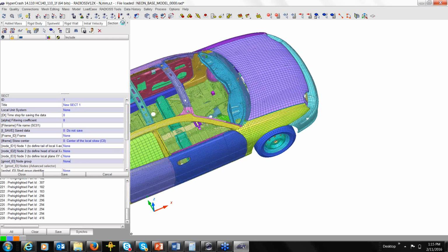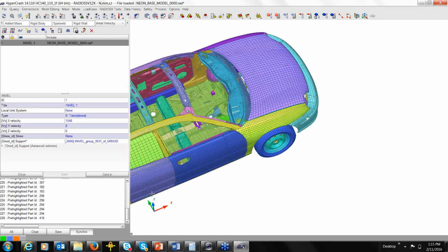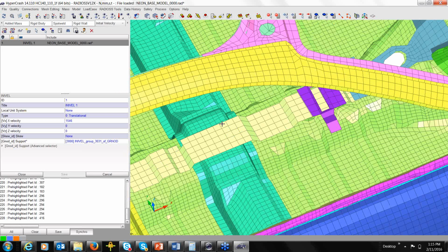The next question is, can we add 1D elements in type 7 contact? Very good question. No. As I mentioned earlier, type 7 is node to segment. Surface segment. I'm talking to myself again. Yeah, so it's a node to surface segment. So that being said, 1D element will not be used for type 7.